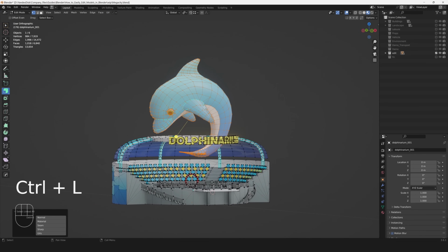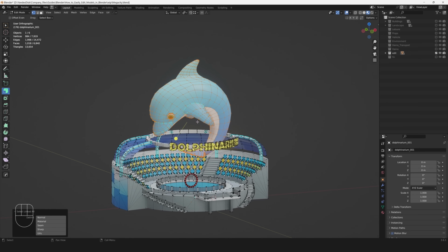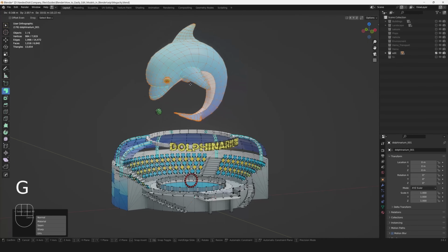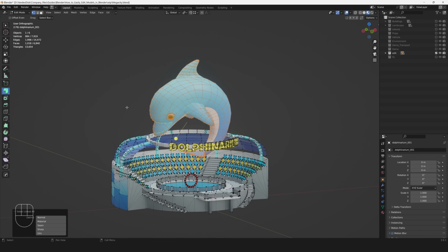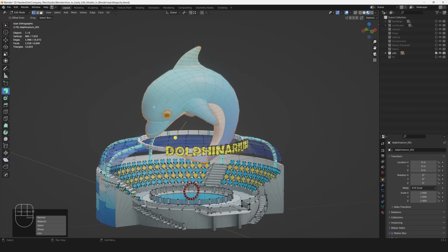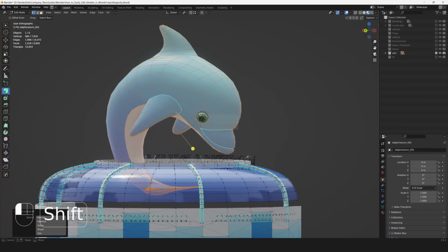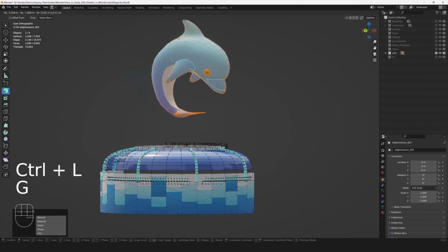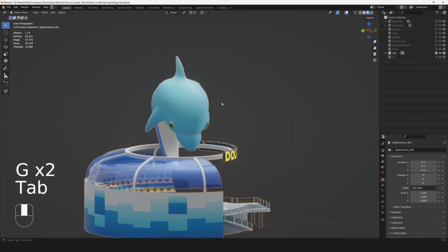It's a little bit more complex because we have not only one geometry as our dolphin to separate, but we also have his eyes. And there are 2 ways of handling this in edit mode. The first way to select multiple geometries is to select firstly one geometry, and after this you can select another geometry, and the third geometry. We have 3 geometries because it's left eye, right eye and body. We can select them from different views and that will make no problem.